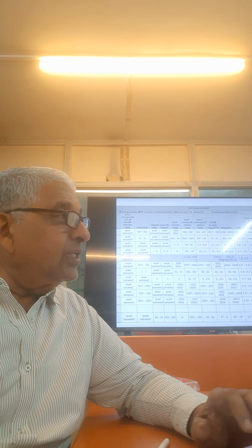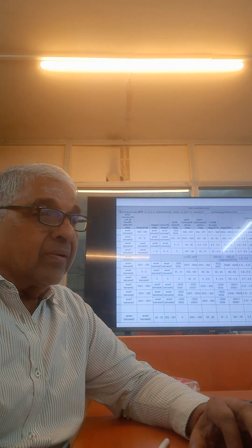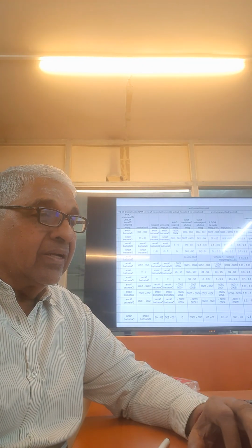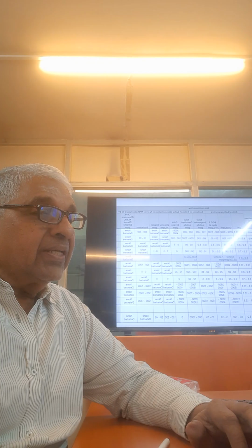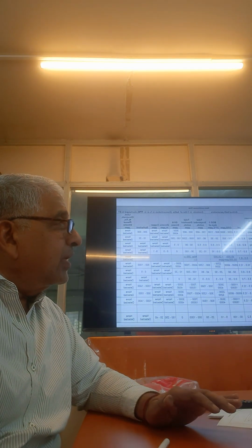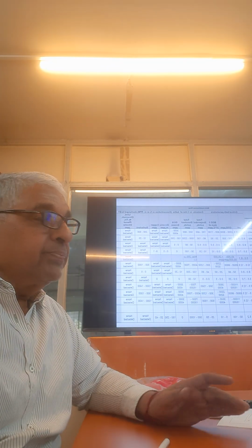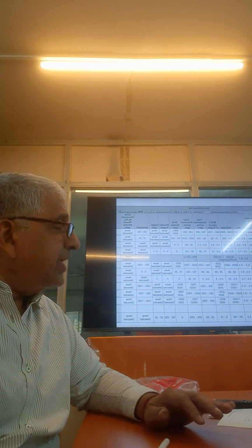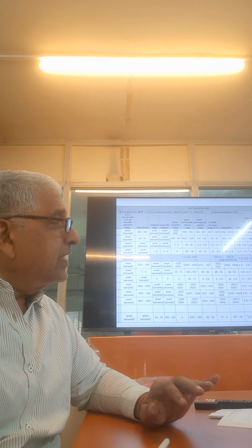Now, if somebody is opening both on the same day, then my maximum will be 59 KL, 60 KL. That is why I said if I lower the collection tank volume by 70 KL, then I can pump this even if it is on the same day. Or if they take it on alternate days, it is that much safer.